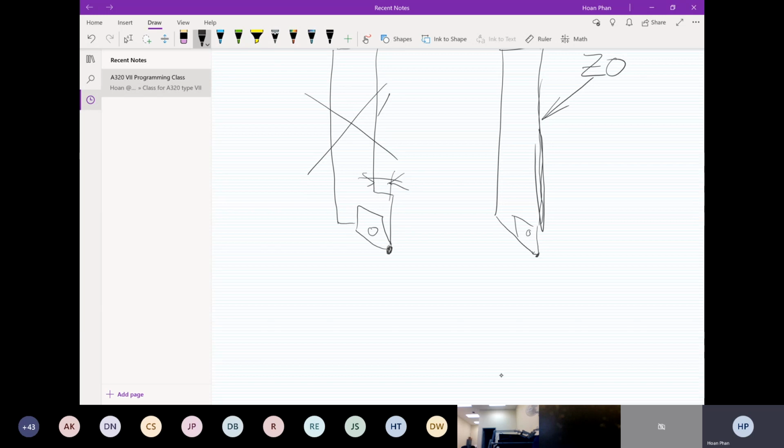So if in some cases you really have to use the tool, you don't have any choice, make sure the distance right here is less than 3 millimeter. If it's more than 3 millimeter, you cannot use the tool. Because if you put the tool in, this face is gonna go against the Z0, and this sticking out, when you go down, will hit the guide bushing. So this is a no-no on the Swiss lathe machine.